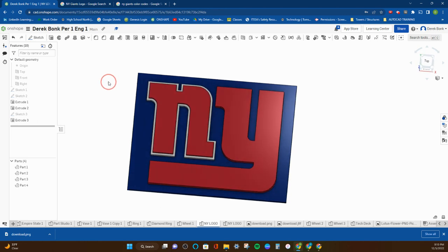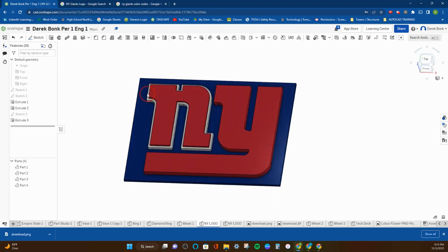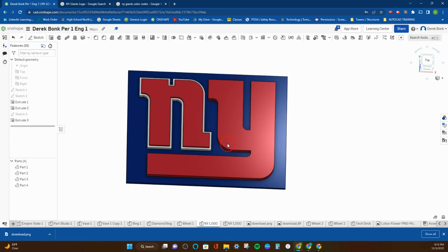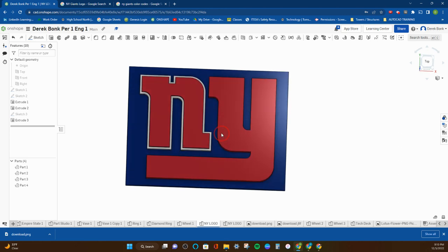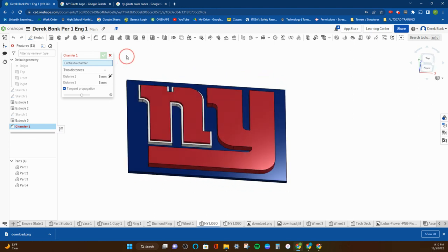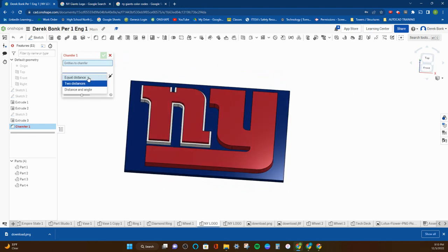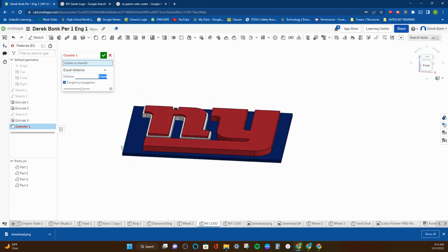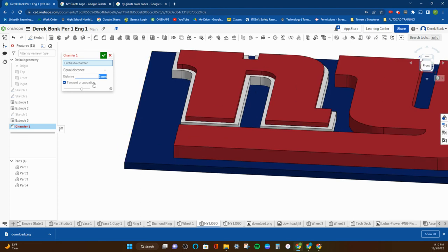and anything that I don't need, including even this little origin point button, to make it look a little bit more pro. One last fun thing that I like to do at the end of projects when I have something like this that's tied together with a plate. Sorry about missing the outside of the Y in white here, but you get the point. You can click these 3D modeling tools. And actually, this is still set up from earlier. Equal distance is what this is going to start at, and this is going to say 5. I made this back plate 3 millimeters thick, so I really can't go any greater than 3 millimeters here.